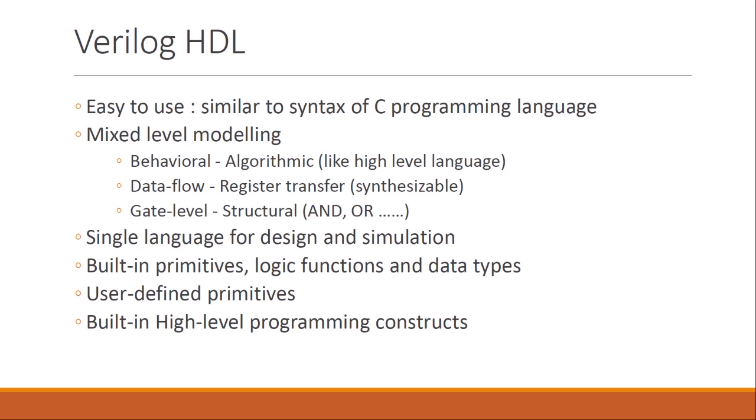Another benefit of Verilog HDL is that it can be used both for design and simulation. It's a single language that can be used for both. How you can do this design and simulation, we'll look into later. It also has built-in primitives, logic functions, data types, and you have the option to have user-defined primitives.